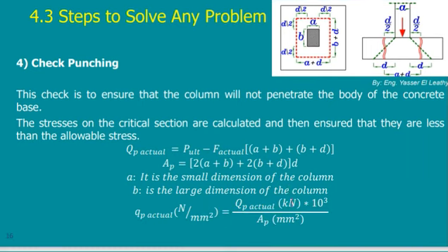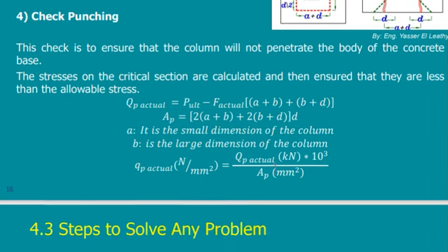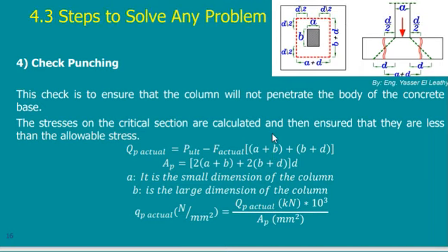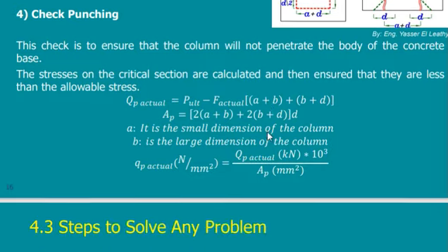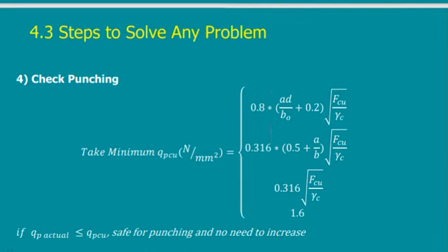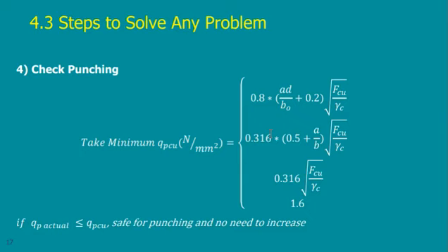Once I have calculated, of course, I'm just giving you the formulas just to know them. You are not going to be asked to calculate steel because we are geotechnical. We are not going to calculate the steel. We will just calculate the punching stress and compare it to the allowable. If it is safe, then we can go to the next step.